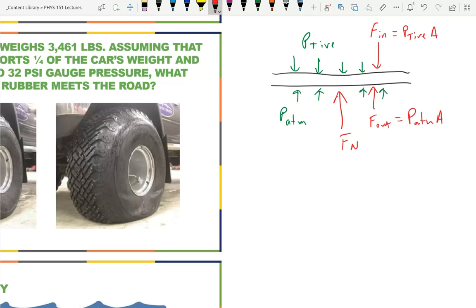So now if I look at this piece of rubber, if the car is, let's say, parked. Let's just keep life easy. If this car is parked, is this a dynamics or an equilibrium problem? Equilibrium. So if it's an equilibrium, then my conditions are things like sum of the forces equals 0. So the sum of the forces, and obviously I'm going to sum this in the vertical direction.